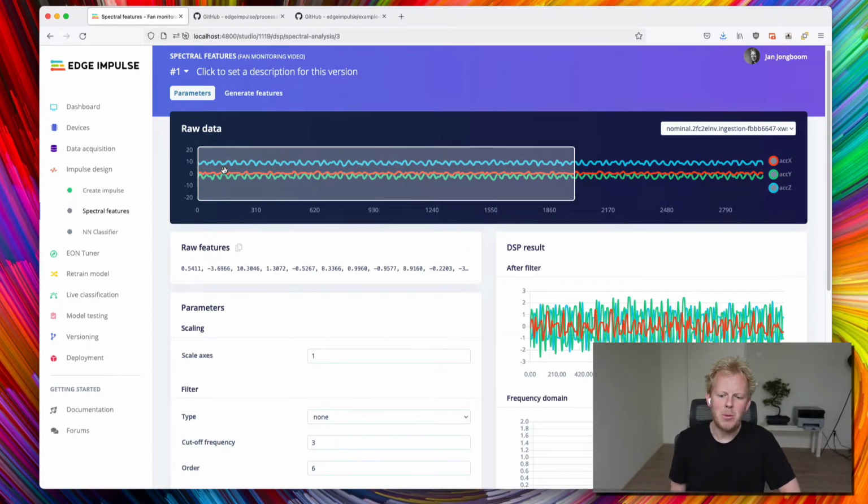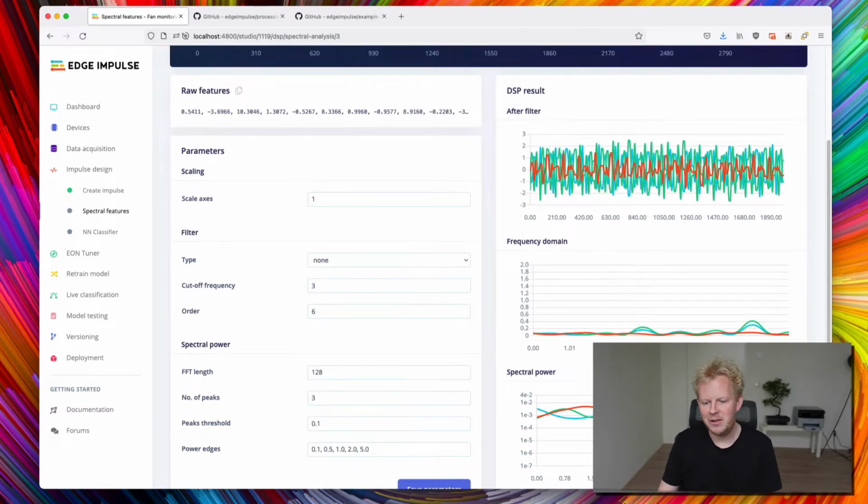What we're probably more interested in is to see the energy per frequency band. So, for example, what is the amount of energy between 1 and 2 hertz after an FFT, 2 and 3 hertz, 3 and 4 hertz, etc. So this block almost does what we want because it does an FFT and then spectral power density, but we want our buckets to be more well spaced. So how hard is that?